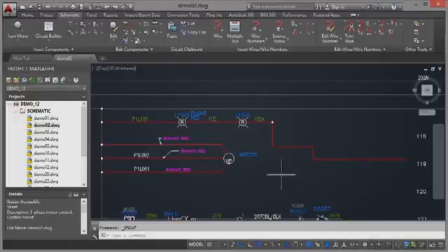Now, in the drawing itself, you can see the pilot lights that we've added here. What we're going to do is add a 3-phase motor to the end of this wire here, and then we're going to put the motor starter contact in and build a parent-child relationship between the two. It's very, very easy to do because a lot of it is parametric and automated. You don't have to worry about the links in the database in the project behind the drawing. AutoCAD Electrical does that for you.